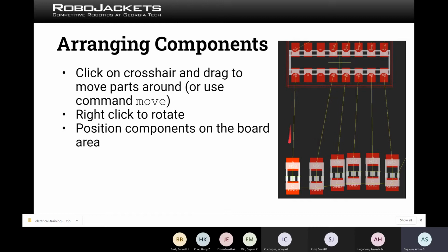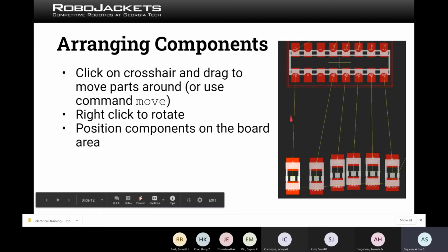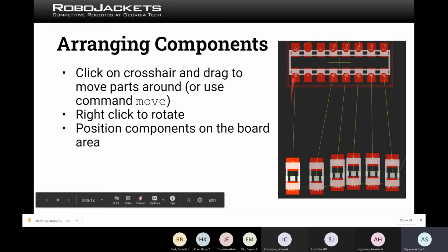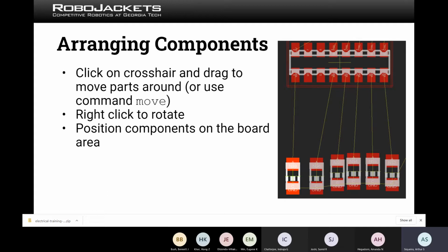These are called air wires. Air wires show from which pin to which pin you should be connecting. They're not actually connecting anything on the physical board. They just indicate from where to where you should connect your signals, in the smallest Euclidean path.